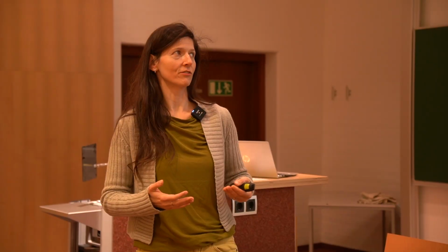Then after rejection of those chips, we are left with parts that very likely have a lifetime that can be predicted. And then there is the final test, which tells us which of those parts have survived the burn-in and can be shipped to the customer.